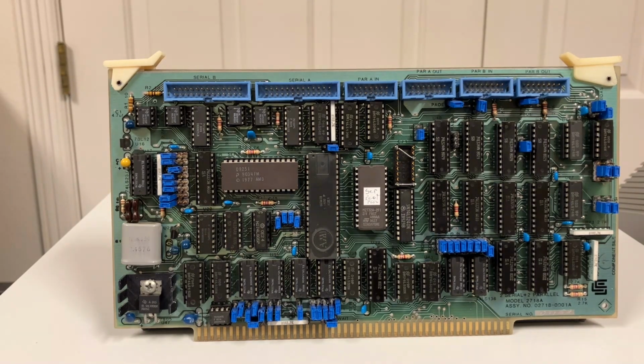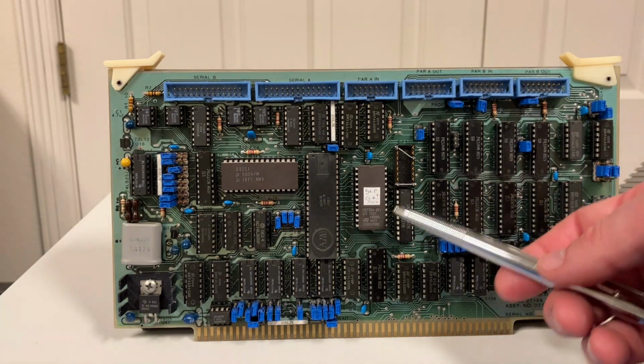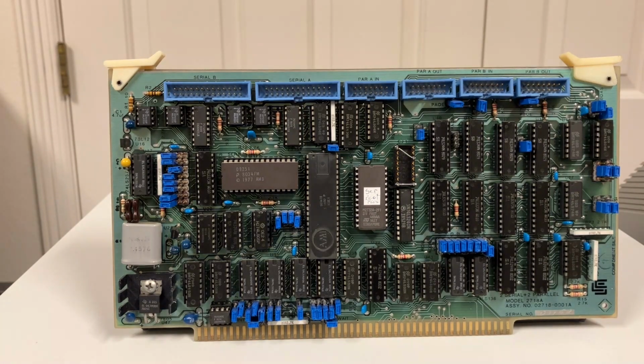And frankly, even if you didn't do any of that, it's probably going to look like ones anyway, just because that's the way TTL works. So anyway, if you have no EEPROM in here at all, everything will return FF, so this board will never drive the bus for whatever address you have selected. If you only had one EEPROM, like Altair size at FF00, just 256 bytes, everything below that would return FF. None of that would actually activate on the bus either. So you don't actually have to lose much address space if you're not using the entire EEPROM. Just kind of a cool trick.